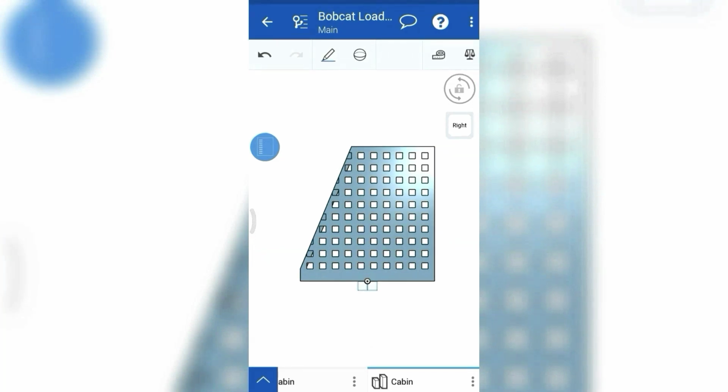Here you can see that the squares are disturbing some part of our design, that is they are overlapping with the edges of the cabin. So we will fill material into these places in order to make a better design. For that, once again we will select the right face and draw a sketch.